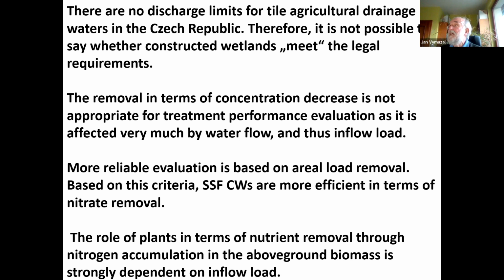Quite important is that we think that to evaluate the effectiveness of these constructed wetlands for removal of nitrogen and phosphorus in terms of percentage, that means the comparison between the inflow and the outflow, is usually not appropriate, because much more important is the load removal. That means the grams or kilograms or tons per year, because this is always affected very much by flow.